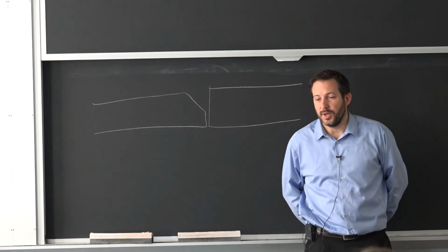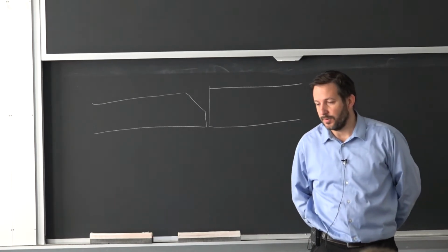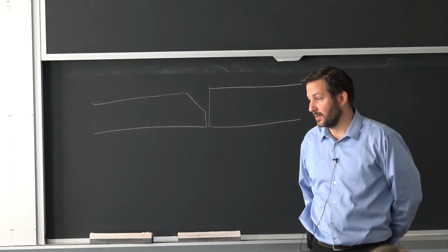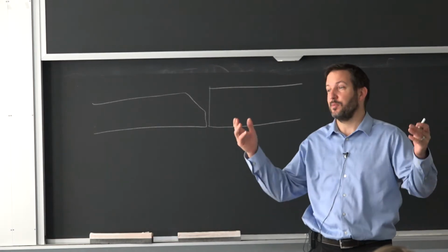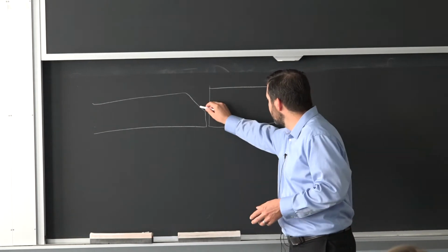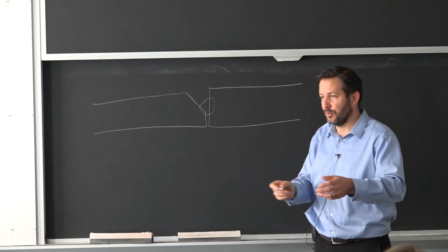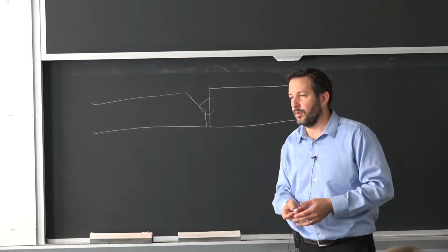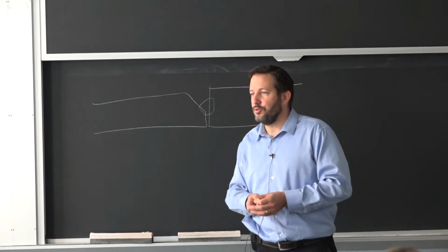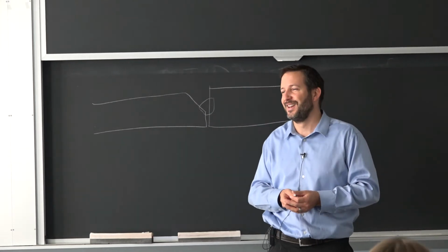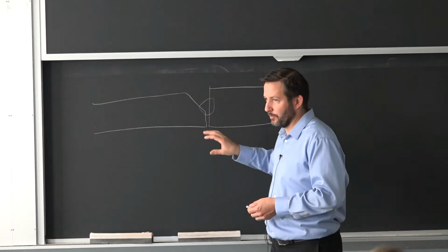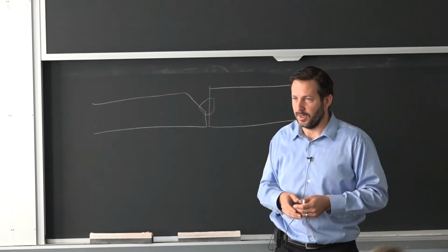That's when I talked about the example of the radio telescope yesterday. That's what they did. They had the entire assembly made with just small welds. Something goes wrong. Let's say I put a little weld here. You just grind it off. Move things around until you're happy with everything in terms of geometry. If somebody says, well, I would rather use bolts, for example. Well, with bolts, you do have to drill in the two components. First of all, you can't really make a butt joint like this. You need a lap joint.